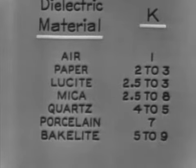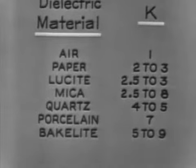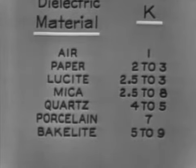Now, I'm sure that plate area and distance between plates requires no further explanation. However, I'll give you a better understanding of what is meant by dielectric K. It all starts with air as the standard. Air is given a K value of 1 and is considered the poorest dielectric in use.